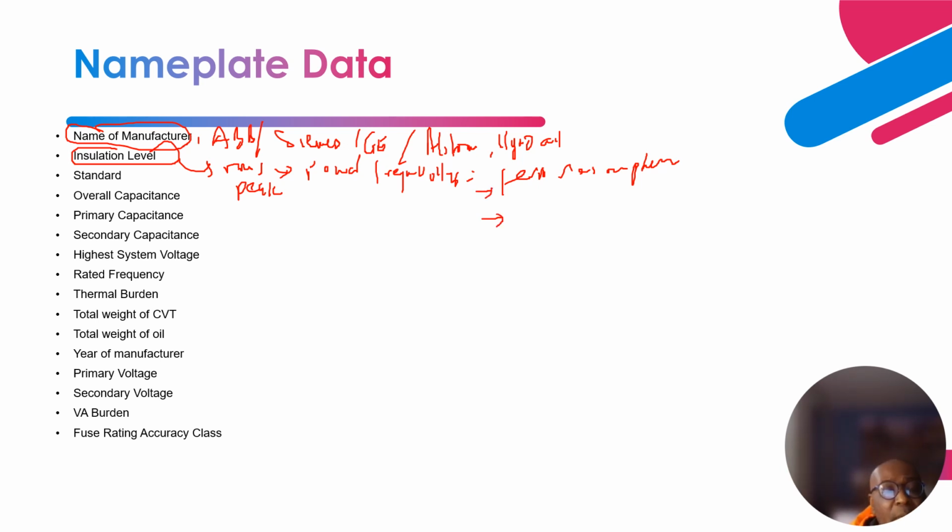Another phenomenon that can cause an RMS power frequency over voltage is load rejection. Let's say during a load shedding condition, you can have a power frequency over voltage condition. The next one is fault clearing and voltage recovery, which can also result in a power frequency over voltage condition. These are just a few that can result in a power frequency over voltage.